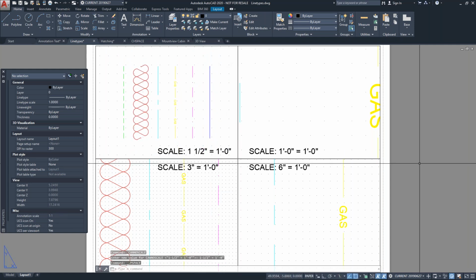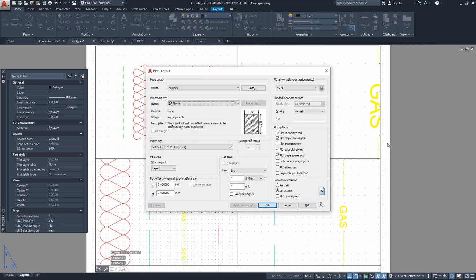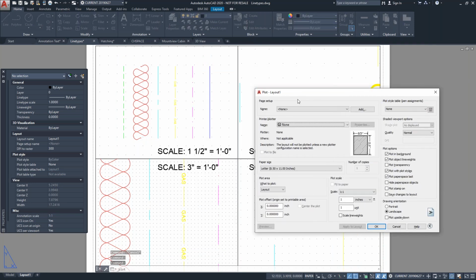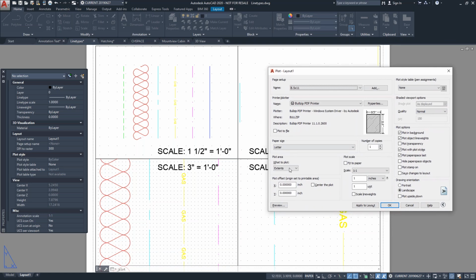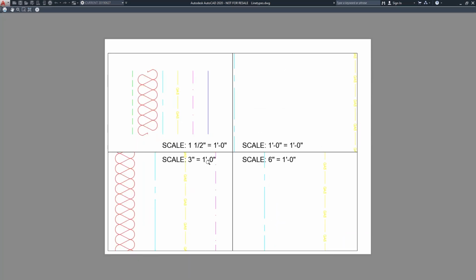And if you accidentally forget to regenerate before printing, the print process actually does a regeneration for you before printing. So that's okay if you forget to regenerate. The printing of a document will automatically regenerate your document for you. So if I click the print dialog box and do a preview, even before setting the scale factor to regenerate, it regenerates all of these viewports automatically.